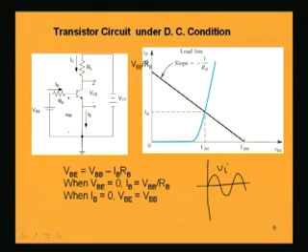That means, I expect a waveform V naught which will be like this in nature, that is the magnitude is amplified many times, but the shape is exactly the same. If it is a sinusoidal input, I must get a sinusoidal output at the collector end. If it is triangular, I must get a triangular. Of course, this will not be exactly in the same phase, as we will find later, it will have an opposite phase. That means, output voltage in common emitter transistor will be out of phase with the input. Basically, this will be the signal.